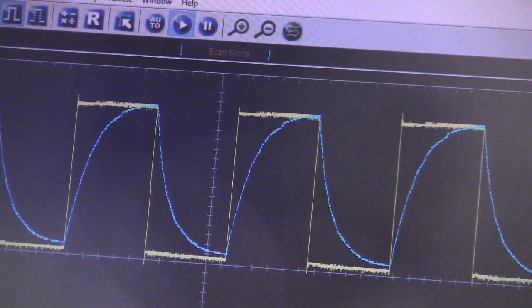Let's review the capacitor charge waveform. We feed the square waveform to the capacitor. In the beginning, when the waveform voltage is 0, the capacitor is also empty, 0. And by the time the waveform voltage is going up, it goes up very sharply, immediately to the top of the full voltage. But you see the capacitor is charged slowly.